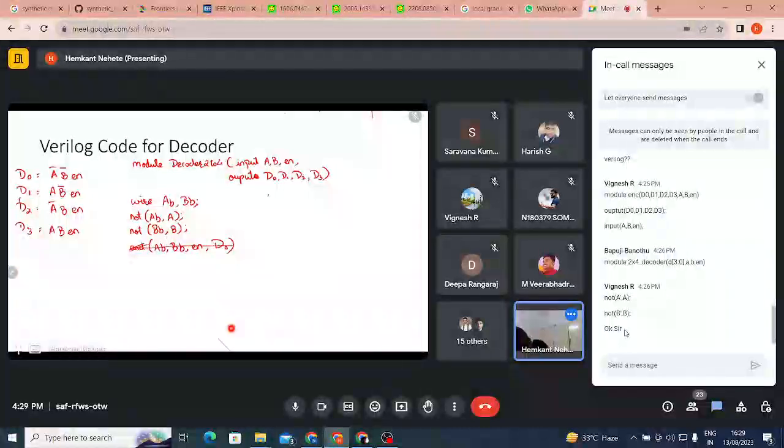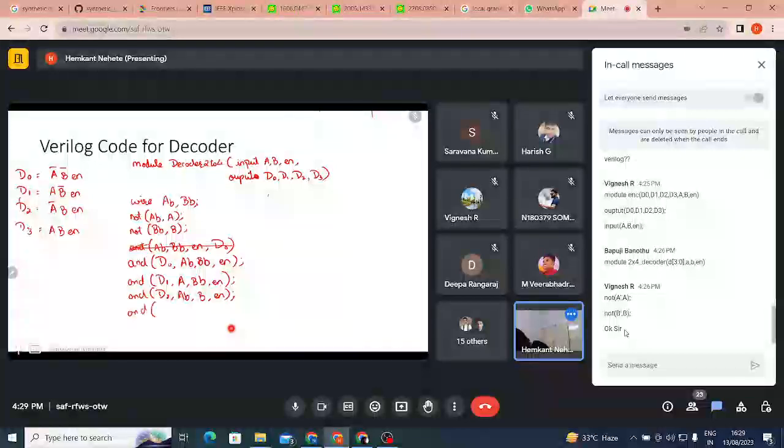So, AND D0, A bar, B bar, enable. And D1, A bar, B, enable. And D2, A, B bar, enable. And D3, A, B, enable.